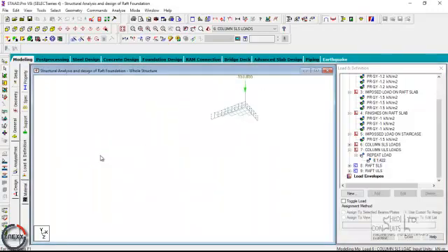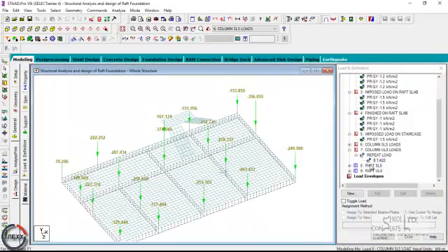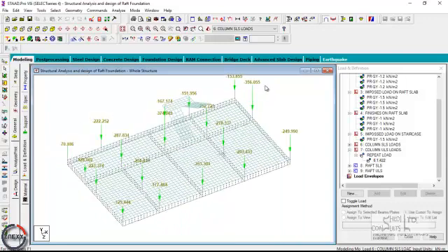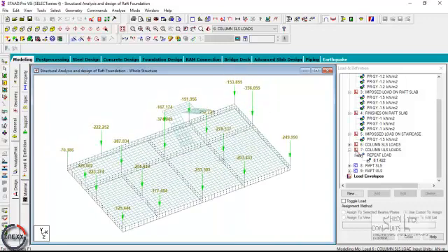The column load under ultimate limit state condition is simply the serviceability limit state load times 1.422. So load case 6 times 1.422 was used to get the ultimate limit state load combination, the ultimate limit state concentrated loads from the column.